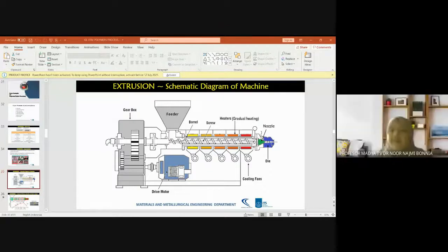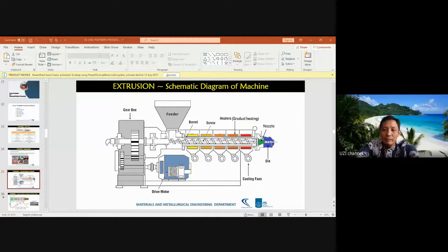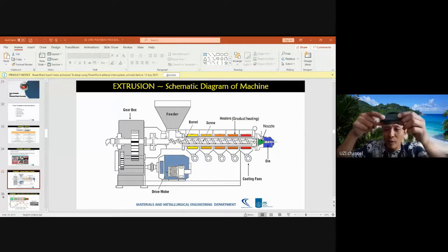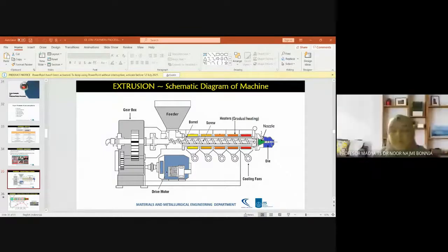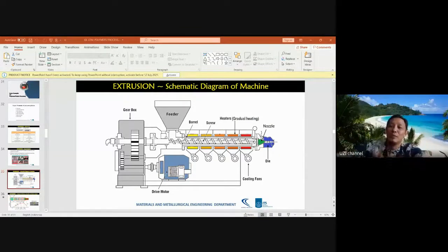Okay. How about the production rate? If we use the melting paste, one product depends on the size. For example, something the size of a mouse, like this one you can see, maybe we need about 2 hours. It can be 2 to 10 hours, depending on how we design the density of the product. The higher the density, the more precise and accurate the size, but the slower the time to produce.